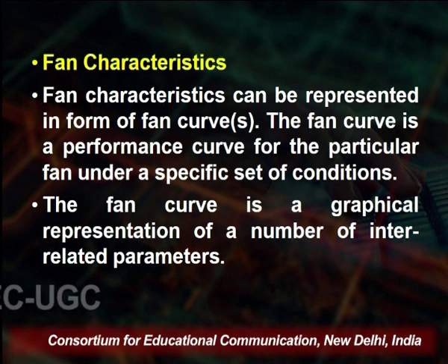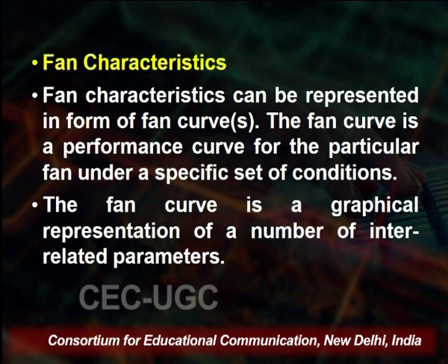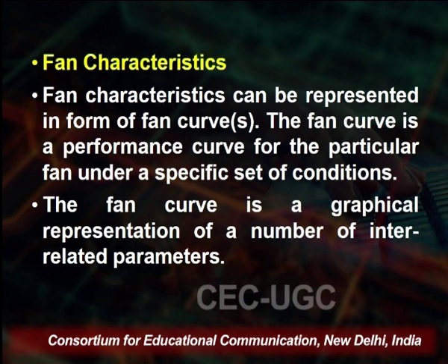The fan curve is a graphical representation of a number of interrelated parameters. Typically, a curve will be developed for a given set of conditions, usually including the fan volume, system static pressure, fan speed and brake horsepower required to drive the fan under the stated conditions.